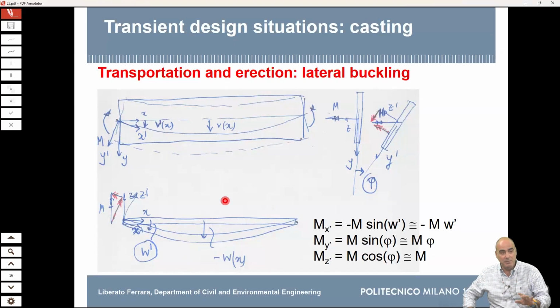So it's extremely important in precast structures, also because precast structures are more slender. We have said yesterday, you have larger spans, you have taller columns because you have better materials and better quality control. But more slender elements also means more deformable. So this deformation cannot be negligible any longer. So what we have to do is that instead of writing our equilibrium equations considering the undeformed beam, we must write them considering the deformed beam.